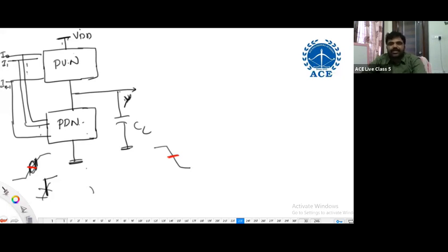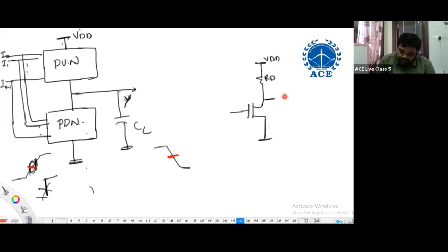Yes, static power is removed. Shubham, excellent, because there is no path from supply to ground to dissipate the power. Simply, if I consider NMOS logic or resistor transistor logic, RTL, this is an RTL inverter. You can use an NPN transistor or whatever be your wish.